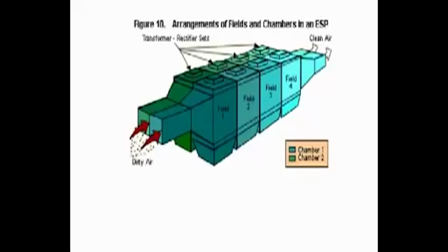The idea of dividing into a parallel process will always have higher efficiency. If something goes wrong in one stream, and things can go wrong, you continue to operate the other one. So that's why generally you will see 2 ducts from the same generator, divided into 2 streams. One goes into this one, absolutely identical, and the other goes into that one, and there will be 2 ducts coming out, and they will be connected to a large chimney part. So that is how your ESP looks like.